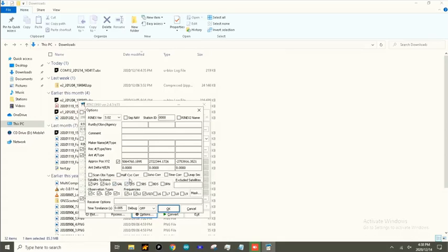I do see that data sometimes pop up on some of the status pages, so I just include that for good measure. Also the approximated XYZ coordinate of our antenna. This can be readily found by just a quick survey in. This just serves as an initial starting point for the optimization software during the post-processing phase. So within 1 or 2 meters, that is good enough. So once we are satisfied with the options, I'm going to click OK.